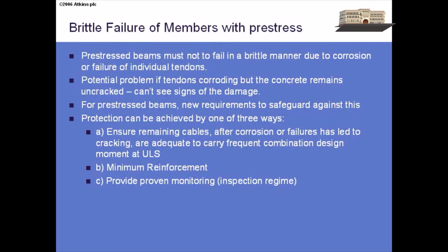And then under that same load combination, you then have to check that, having lost the tensile strength of the concrete, there is enough resistance in the remaining pre-stressing in the concrete at the ultimate limit state to carry that same load combination. So it's pretty obvious, really. It's just saying, for a given load case, work out how many tendons you would have to lose for it to crack, then assume that happens, and does it still stand up once it's cracked and you've lost the tensile strength. If you do that, as I say, you'll almost always prove that it's fine.